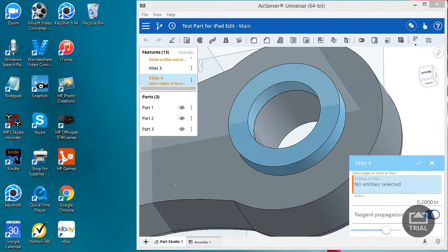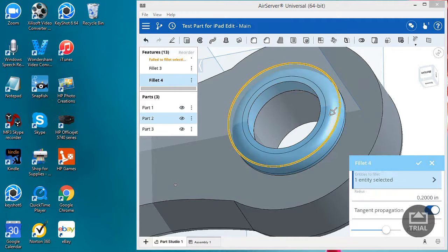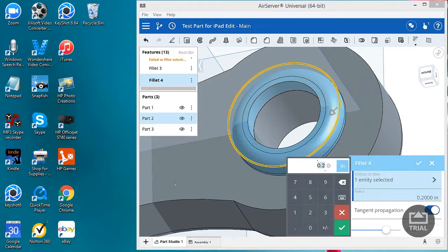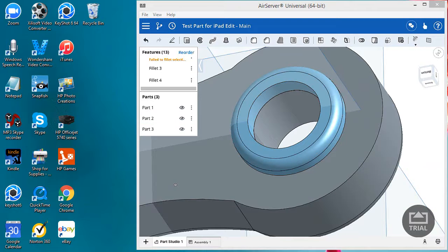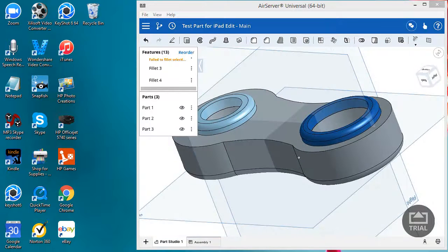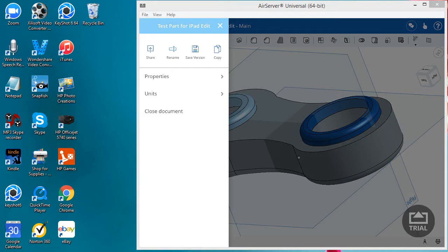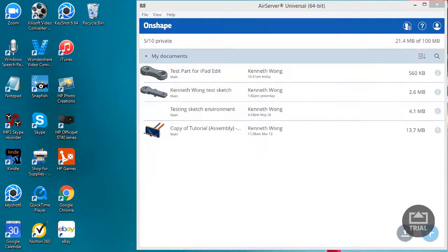So I'm going to launch this project that I've been working on previously. This time I'll be working on it inside my iPad Onshape app. Some operations like sketching in 2D or adding dimensions to your 2D profile, in my view anyway, seem to work a lot better with a mouse and a keyboard, usually associated with working from a desktop workspace. With other operations like extrusion or adding rounded corners to your edges, well, they really don't make a whole lot of difference, so I can also use my fingertips effectively to execute them.